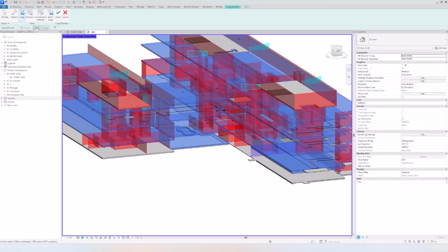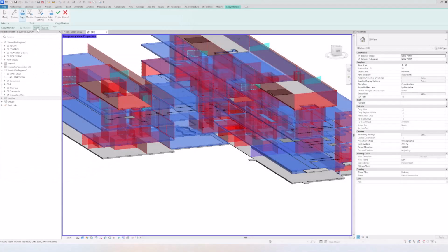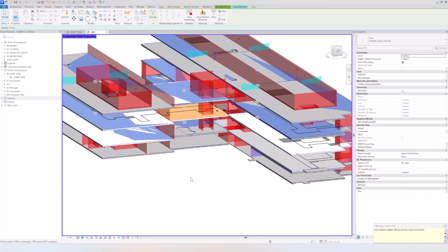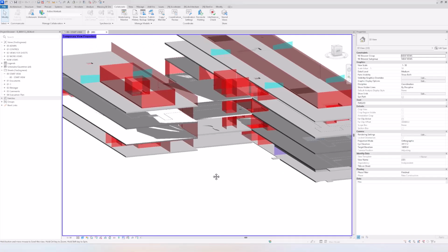And we will, as always, go to the smaller finish before going to the larger finish, and we will copy all these slabs into our model. You select the different slabs using the Control key, if you didn't know that, and everything now is copied into our model, and I will finish the Copy&Monitor feature as well. Now we need to adjust everything that we copied, so it's going to look good.